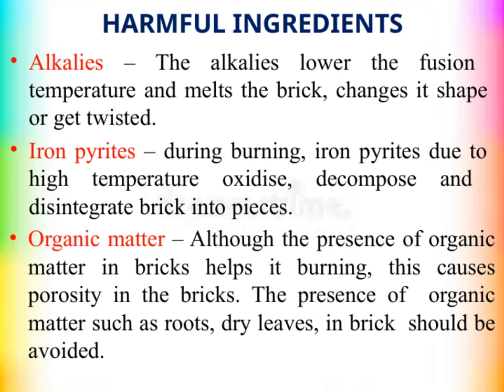Finally, organic matter such as roots or dry leaves can be present in bricks. While organic matter might help in the burning process, it also introduces porosity, tiny holes or voids, in the brick. This porosity reduces the brick's strength and durability. It's important to avoid organic impurities like roots or dry leaves in the bricks, because they can weaken the final product and affect its performance.